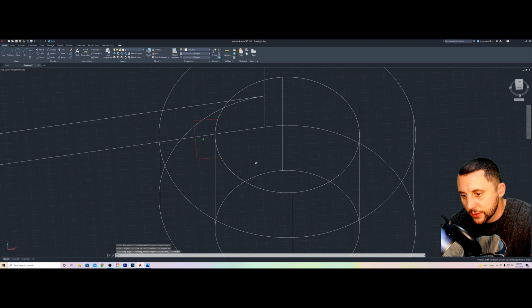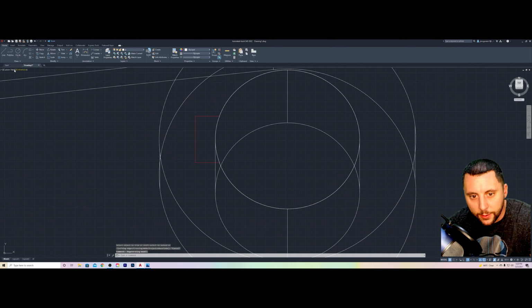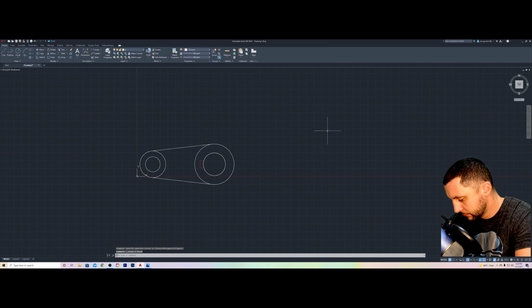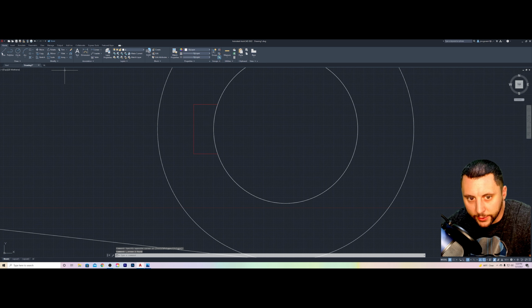So now you can see I couldn't just take a line. Let's go to the top. By the way, this stuff can go. I couldn't just take a line at the edge of this curve here and go 6 over from that. Because let's just pretend I'm going to put this point here. 6 from there would get you out here. But we want the edge of it to be 6, this line. So I had to connect this intersection to this intersection in order to do my offset of 6, okay?